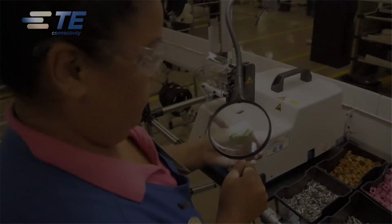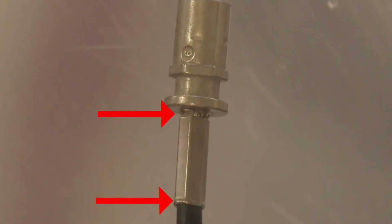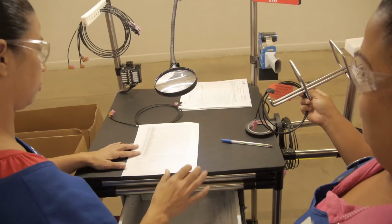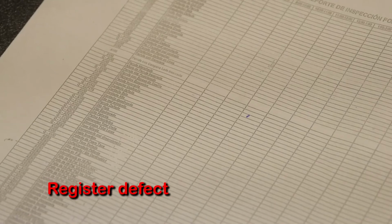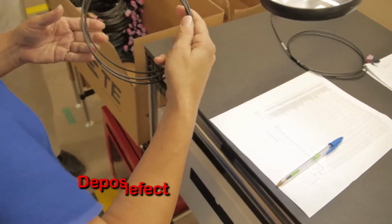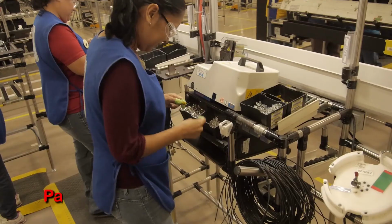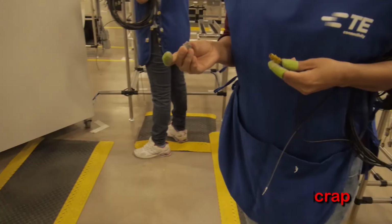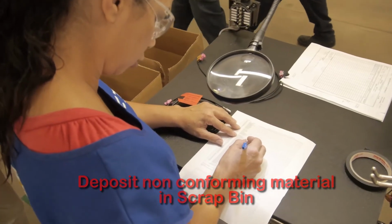Defective product at any of the different operations or non-conforming material will have to be properly handled and dispositioned per TE procedures. A red ticket should be filled out to indicate the type of observed defect for the product, and it should be deposited in the scrap bin. During the assembly process, if components are dropped to the ground, they should be deposited in the scrap bin and registered in the scrap log sheet.